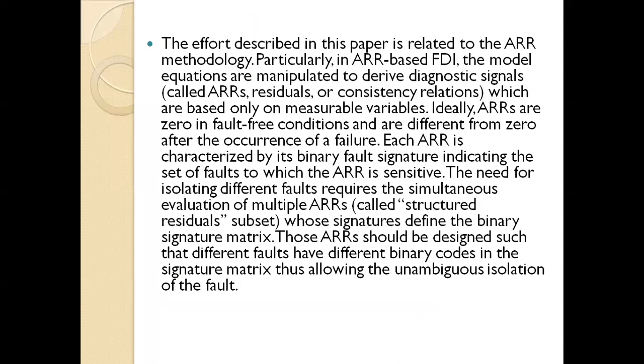Particularly in ARR-based FDI, the model equations are manipulated to derive diagnostic signals, which are based only on measurable variables. Ideally, ARRs are zero in fault-free conditions and are different from zero after the occurrence of a failure. Each ARR is characterized by its binary fault signature, indicating the set of faults to which the ARR is sensitive.